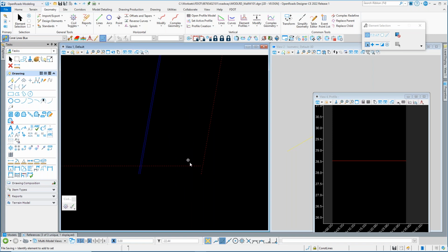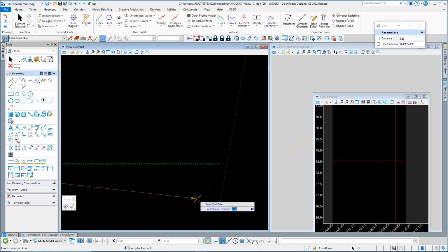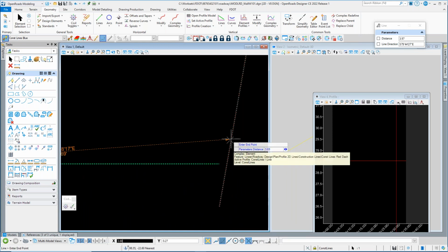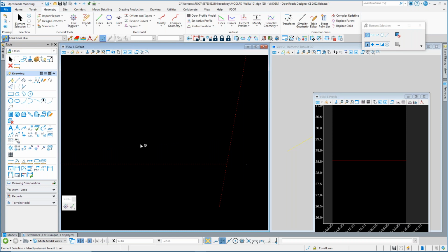We've got to do a little bit of changes to these guys to get them now to also line up. So we're going to grab that element and it'll be the same thing. It'll be hard to actually drag this over an intersect snap. So there again, just grab the end, kind of like a free float on that element, and we'll grab that and intersect that. Same thing here, it's off just a little bit. But here, we're coming right over to another element that we can just snap to the end of it.